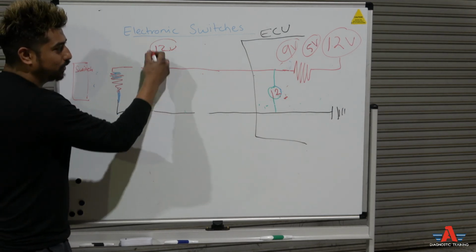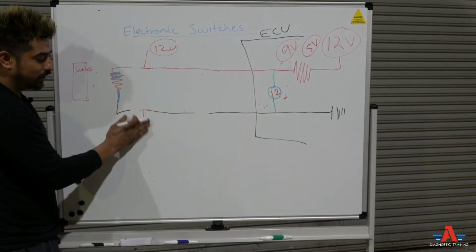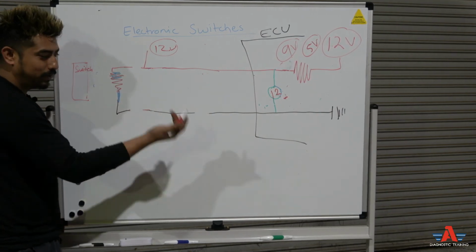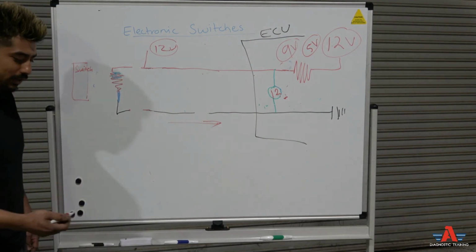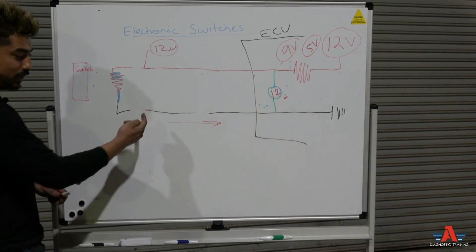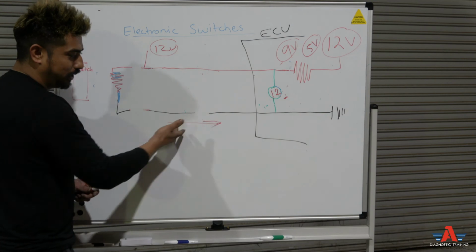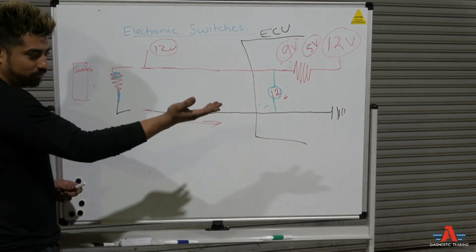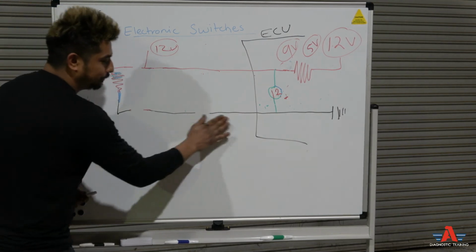Yes, there's a 12 volt. Check here, is there a ground? No, there is no ground. The test light doesn't light up, means there's something wrong this way. Now chase that ground wire. You really might need a wiring diagram, see where this goes to, service information, and do they change color at the computer, whatever the case is, you check that way, right?